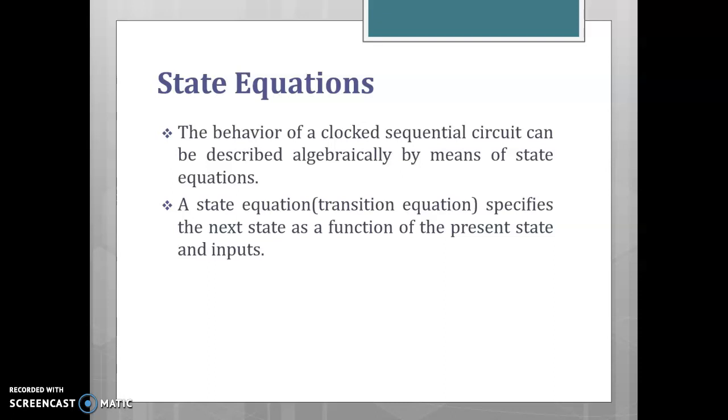The state equation is an algebraic equation that describes the behavior of the sequential circuit. The state equation is also referred to as the transition equation. The state equation specifies the next state as a function of the present state as well as the input.